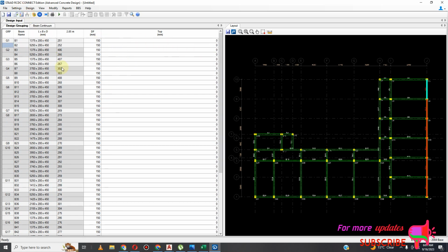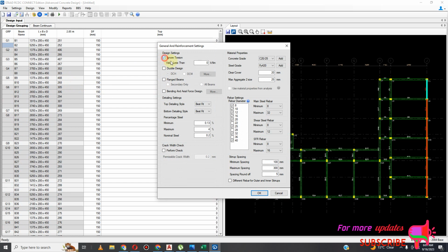Don't worry. I need to ignore torsion at 0.1, and then I want to select all to be ductile, all my beams to be flanged, my class to be 25, full RT, my steel grade to be 550, maybe even 460, it doesn't matter.